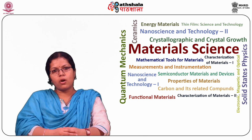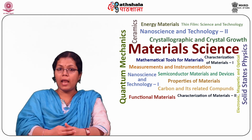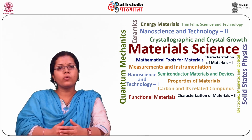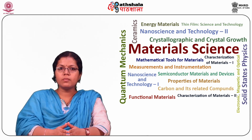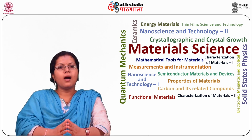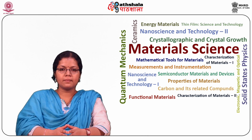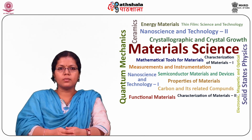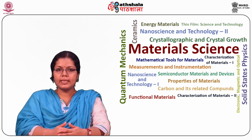Owing to development of materials like Alcomax and Alnico, which have a high coercive force, it is possible to use smaller magnet lengths and high field intensities. Thus, in small instruments, it is possible to use a small coil having small number of turns, and hence a reduction in volume is achieved.